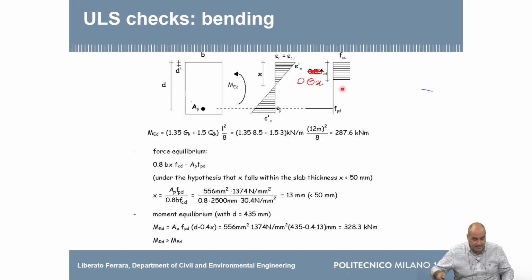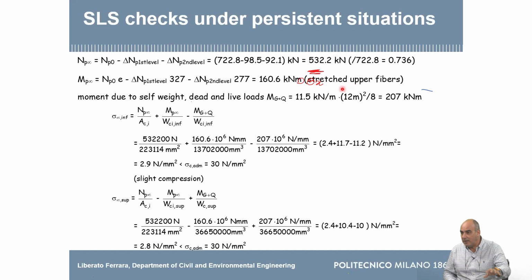In serviceability states, this situation here is what the structure is experiencing. And it's good that the stresses here are low because this controls the creep. One of the issues that you have in precast, pre-stressed elements is exactly the creep. They continue to creep. So if you keep the creep low, it's good because if this element sags too much, your waterproofing upstairs or your finishing upstairs crack.